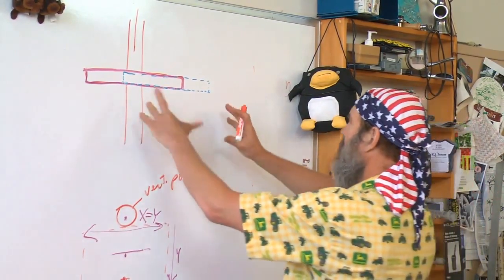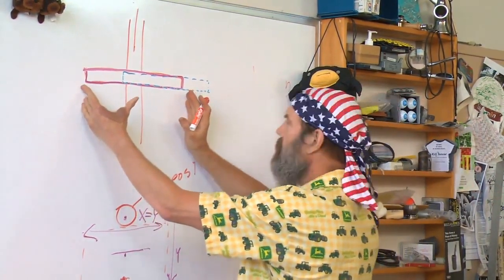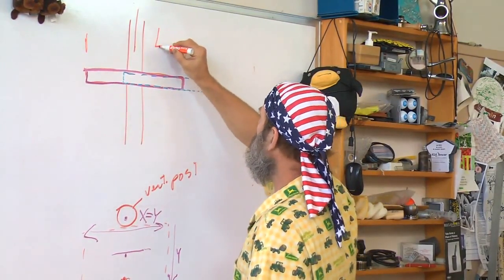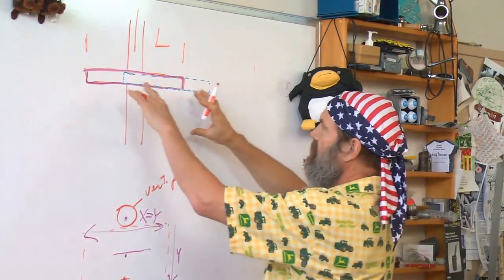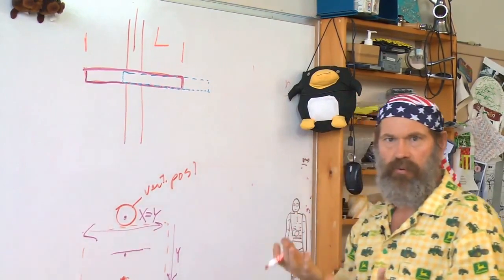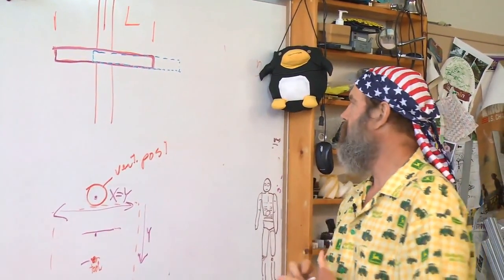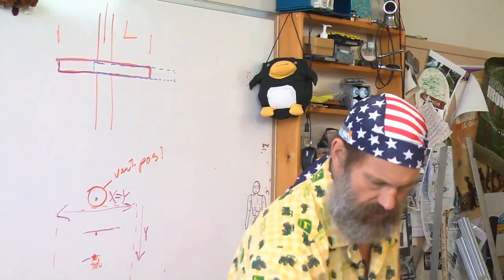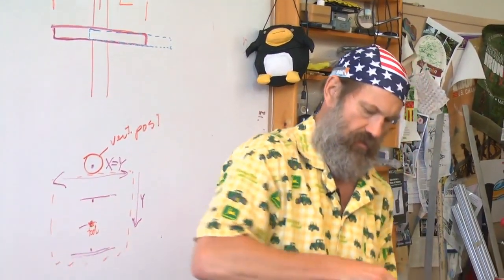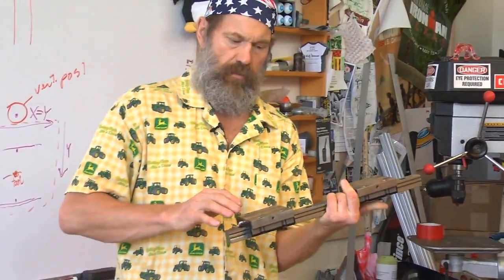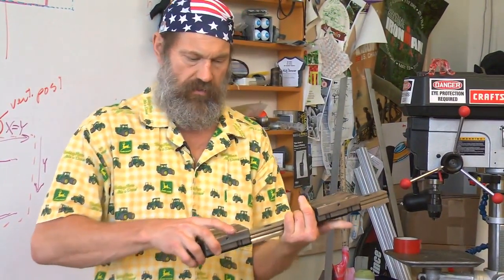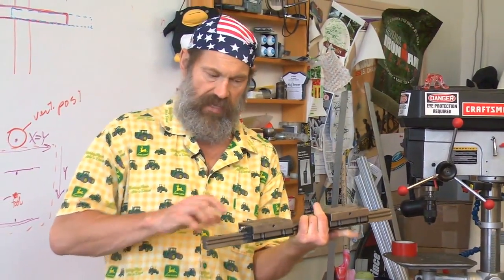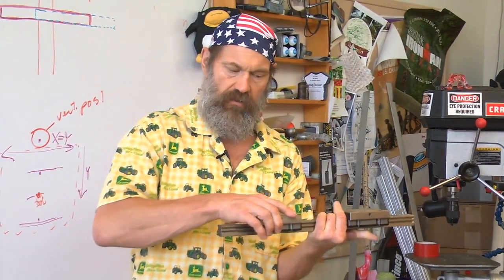Well, I need to have certain proportions, and if this table is L length, I know if I'm going to do linear motion, I'm going to have some bearing support, and I have two options. I can, one, fix, for example, the bearings on the table and have the rail fixed to the base so the table moves on the rail.